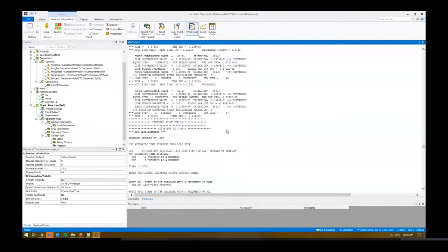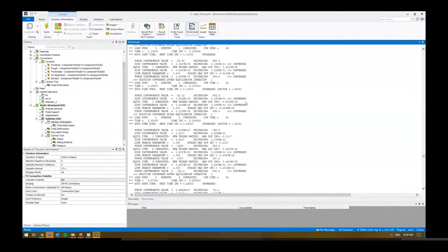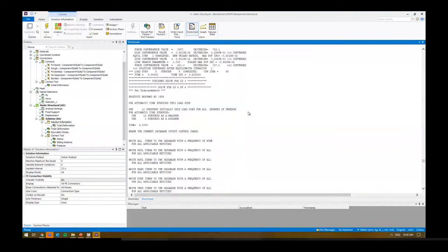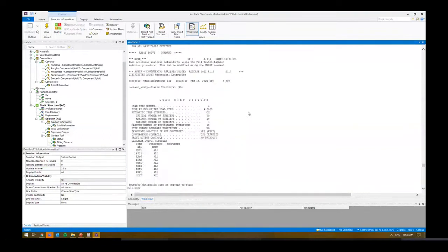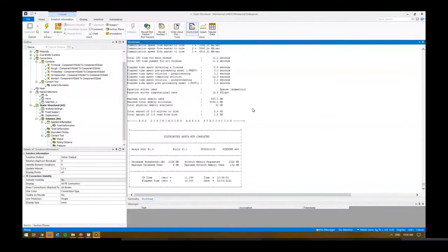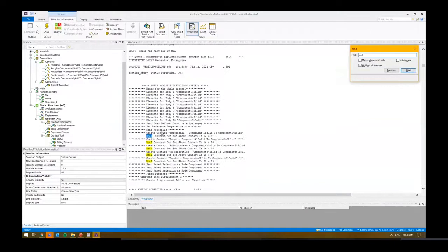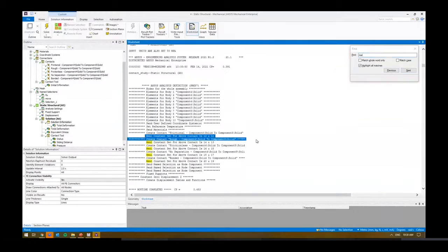One of the things that we'll pick up in a second, so we've got a couple of different models as well. I'll try to find them, maybe try to find what's called real constants. So one of the things I wanted to show you guys, sorry, was, here you go. So the real constants here, constant 12 and 11, are the frictionless contacts that are generated for us, right?